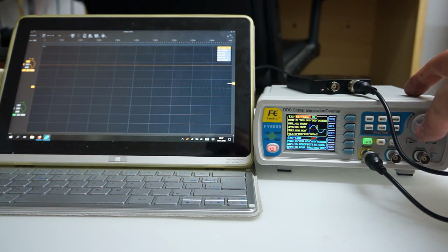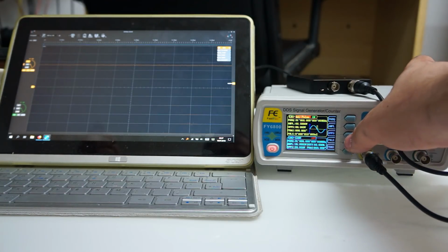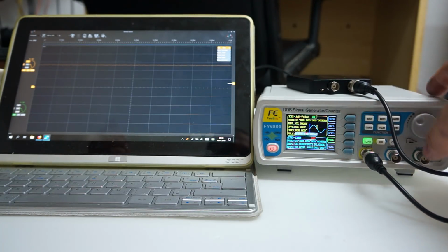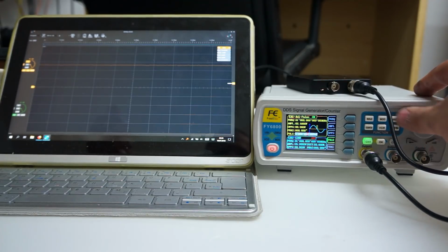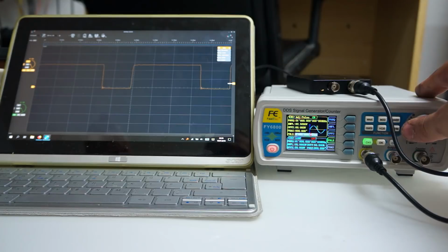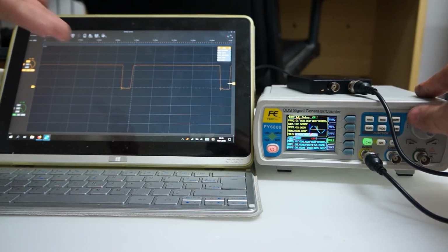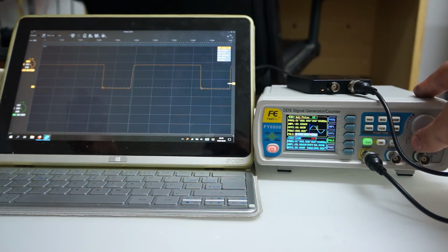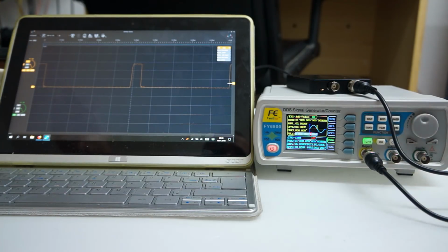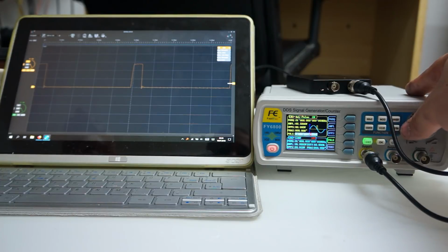That's the adjustable pulse, which works if we change the pulse length. I already changed it, that's why it doesn't show up. We have to change it to a value that's in the range of the frequency. So if we got 1 megahertz and we select the 1 microsecond pulse, we won't see anything. If you go down to 100 nanoseconds, it's obviously 10% duty cycle.